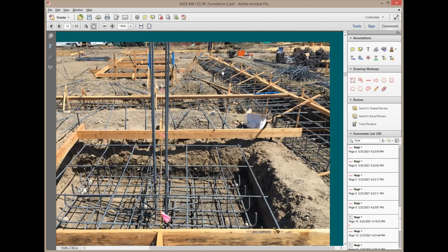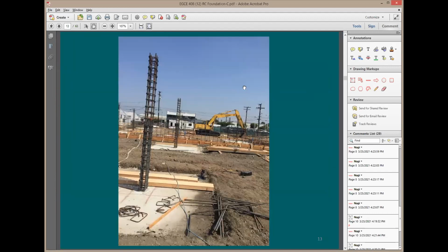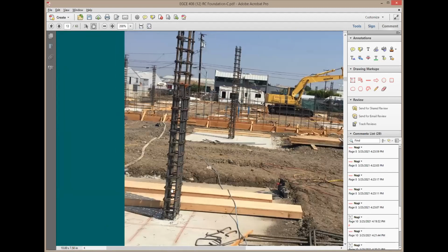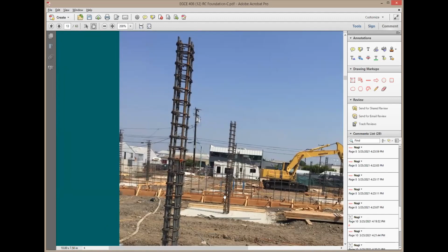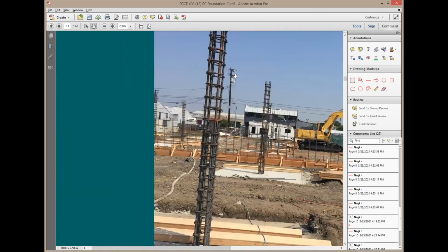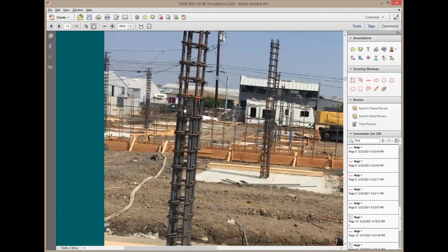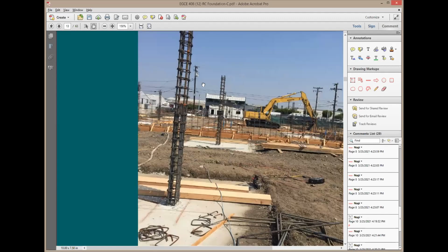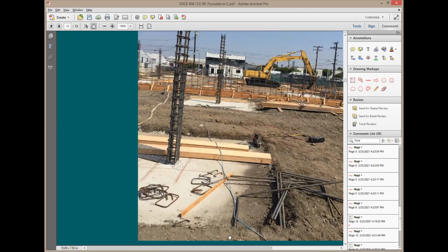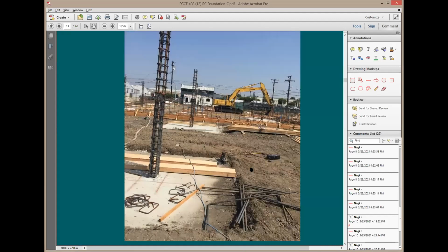Okay. So this is here one of the wall footings, and you see it's going to be like a continuous footing. That was an early stage of construction. And let me show you this after the contractor poured a couple of footings. Here is the concrete, you see here, the dowels of the concrete column stick all the way to here only. And then here, you see the column rebars and the overlap. So you have the 4 rebars inside and then you have some rebars. And you see here, look at the footing. Now you don't see the hole, right? Everything now is filled with concrete.